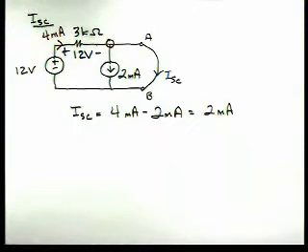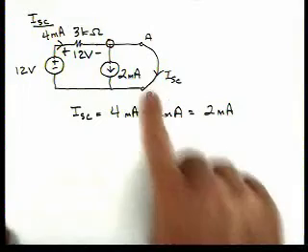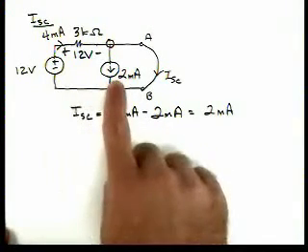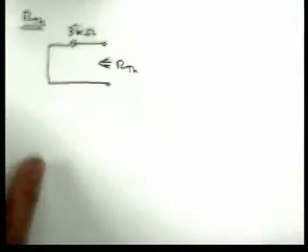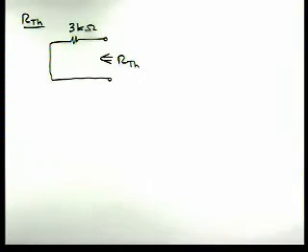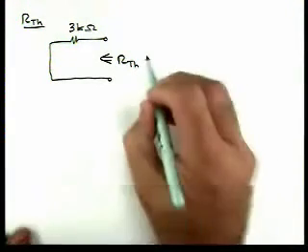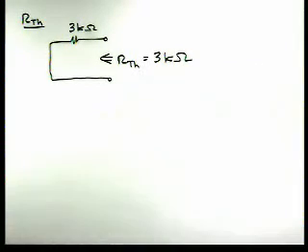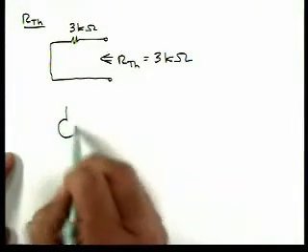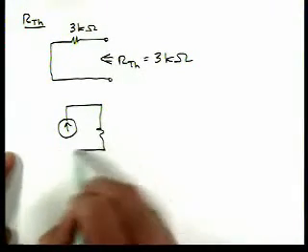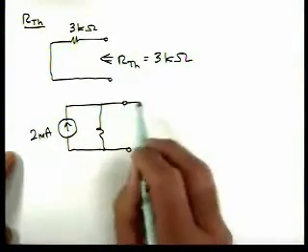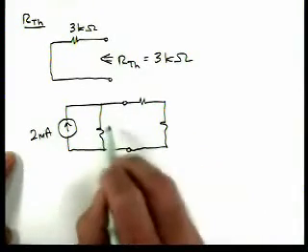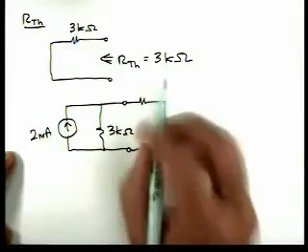And then if we find the Thevenin resistance for this configuration, we turn this source off and this source off. Basically turn this to 0, it's an open circuit, turn this to 0, it's a short circuit, then our resulting circuit is that. So our Thevenin resistance is just 3 kilo ohms. So by breaking it where we did, we simplified the calculation some. So now our Norton equivalent circuit is this. You have 2 milliamps in parallel with a 3K.